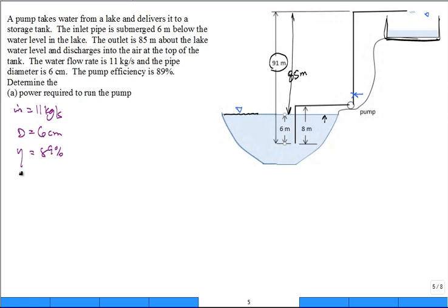Well, you're putting in power here, W dot power to go into the pump. Only 89% of it goes into the fluid. True? Where did the other 11% go? Whooping up the fluid and making it warm, which is not getting it converted into the mechanical energy of the flowing fluid. Non-useful. Or maybe it went into friction that got the surroundings around the pump warm. Okay?